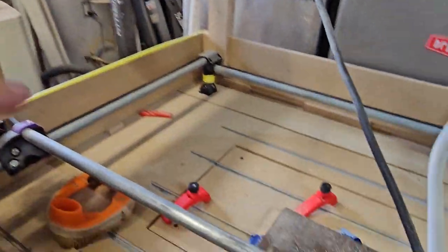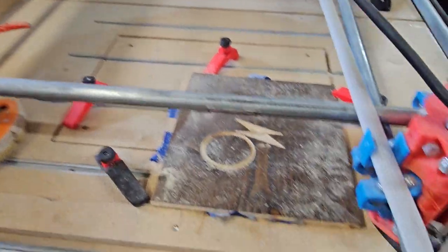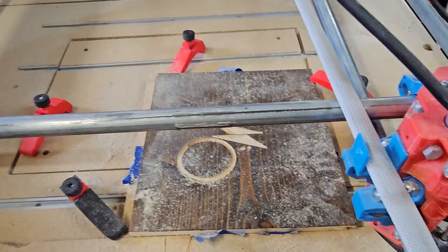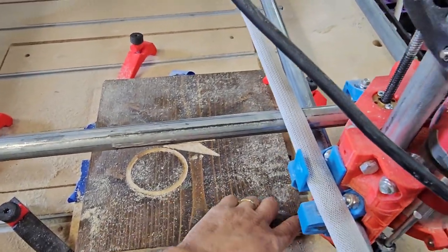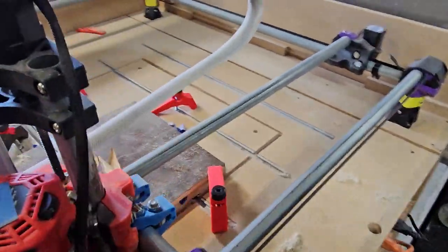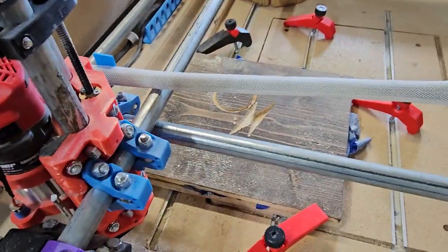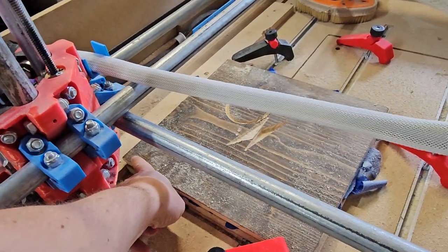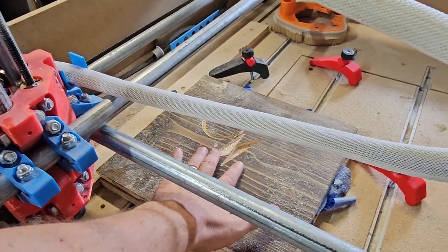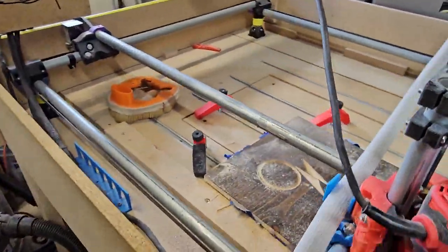So to go from this point to actually working, you have a few more steps to do. You want to now set the origin for your cut, because everything is done based on where that origin is. So last night you saw the way that the machine works, because this is our X, this is our Y. A lot of people origin at the bottom left corner of their material. I'm going to origin in the middle. That's how I set all my software up, all my cuts set up.